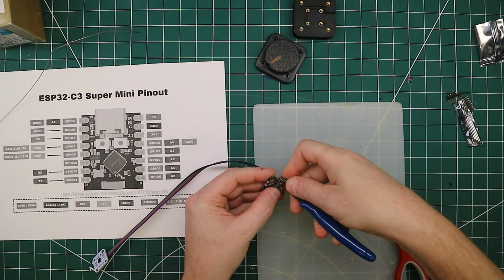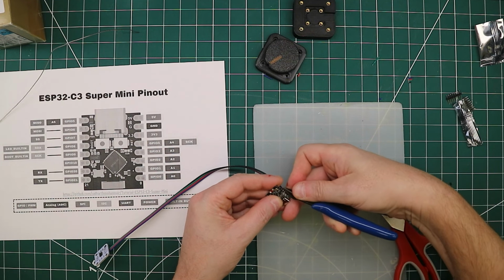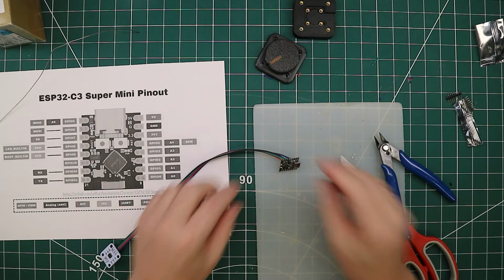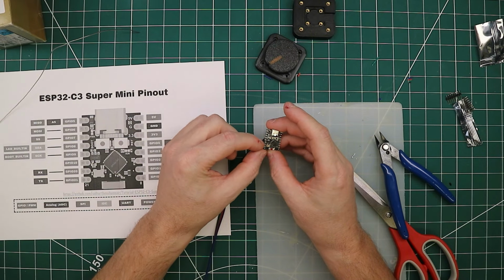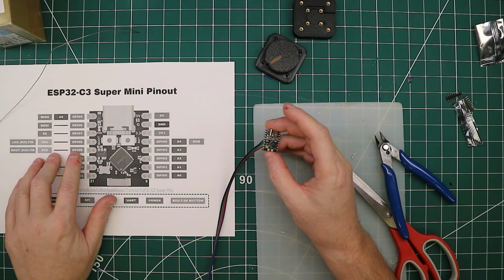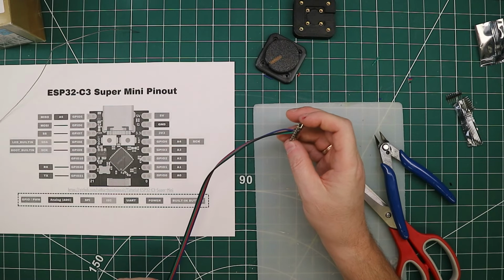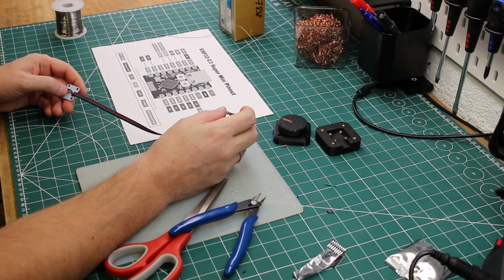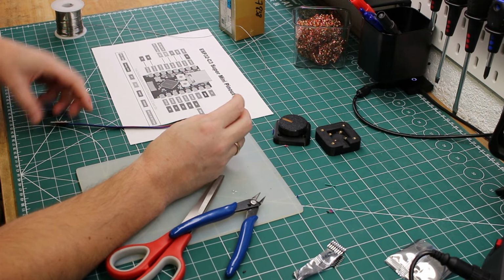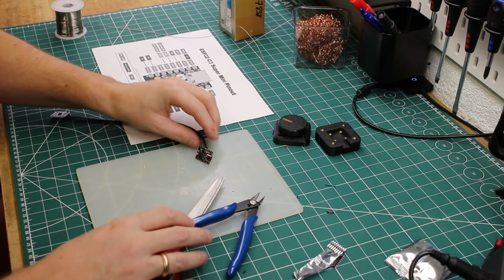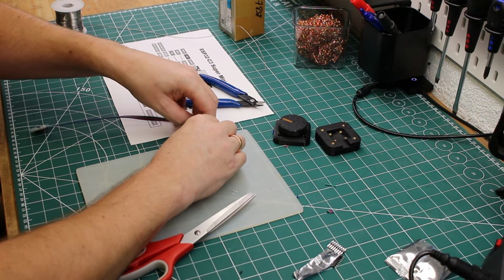Let's just bend these back out into the, I think it's called castellated. I can't remember. If I remember to check, and if I'm wrong, I'll try and do a screen overlay. Could easily forget that. Let's just double check. These are the 3 above and 3 below. That's correct. The top one, or the one closest to the USB, is the data. That's the blue. And the blue wire is connected to SDA, serial data. Yep, that looks all right. Let's solder it up, or at least try.